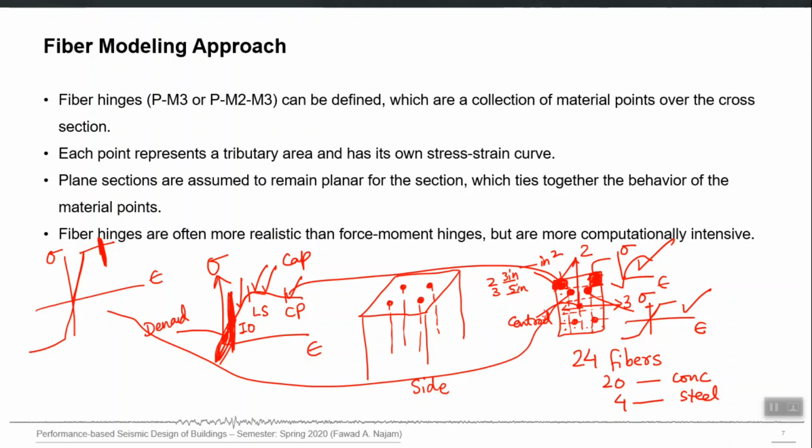So this was a quick introduction of the fiber modeling approach. They are hypothetical fibers, they do not interact, there is no slip or friction or anything between them. They are just divided into fibers for the purpose of assigning individual stress strain curves, right? Now before moving forward, let me quickly explain another useful feature of the fiber modeling approach.